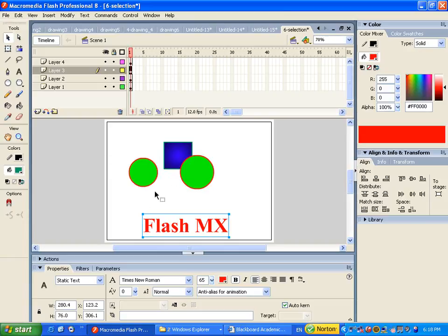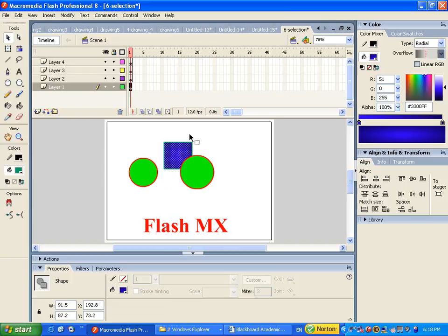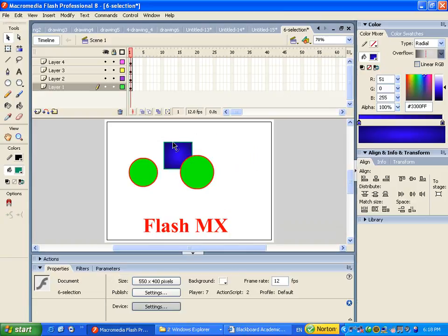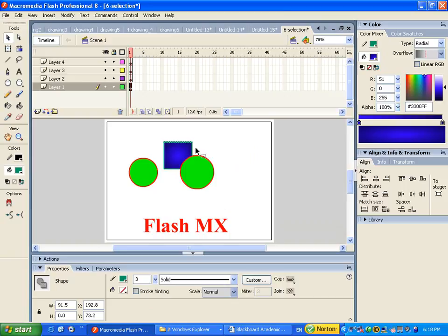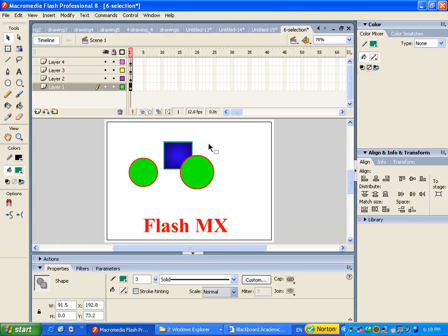One of the selection techniques and rules is that if you click inside an object, and the object is a shape, you now have a selection of the fill. When you try to drag this part, you can find only the fill is moved. And if you want to select a stroke, a simple click on one edge of the stroke can select that edge only. And this is what happens when you click the circle, as the circle is a continuous line.